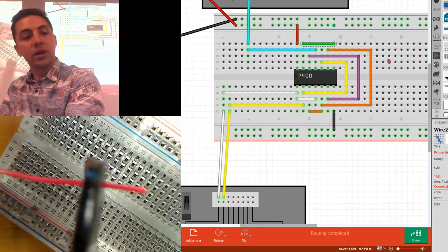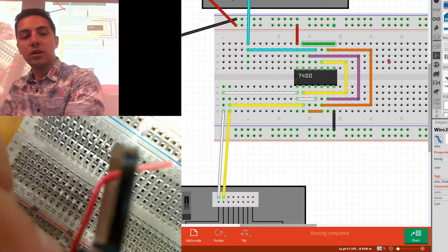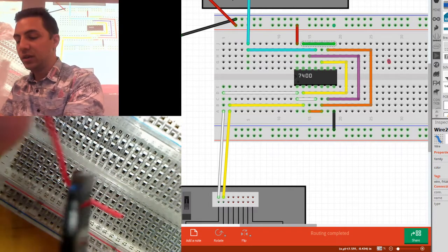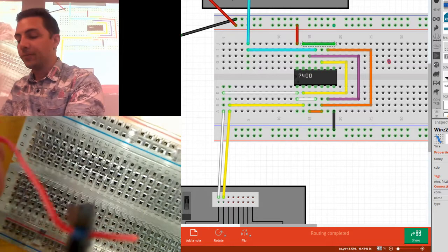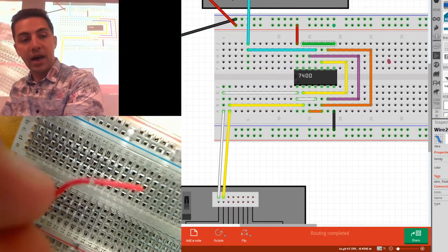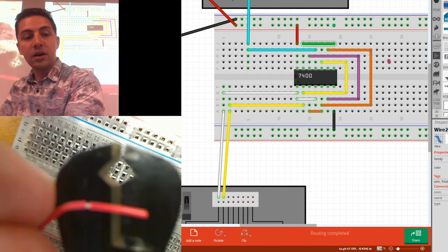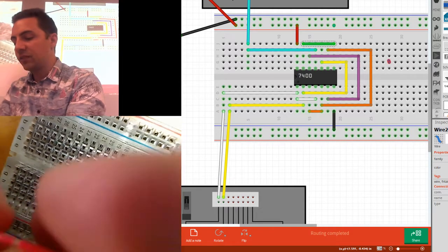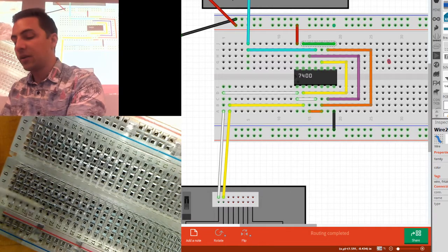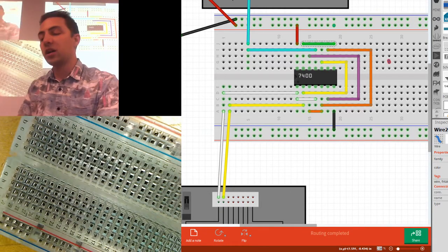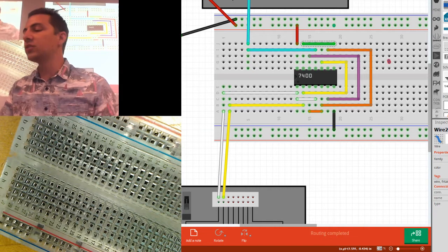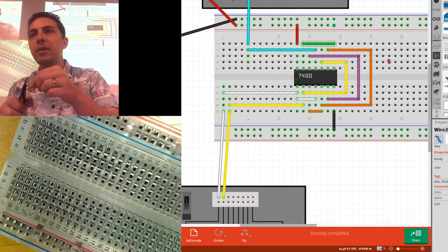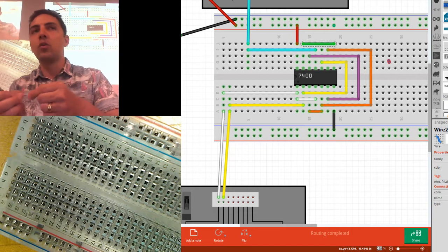So what I do is I put a small joint into it. So now it's bent there. It's also bent on my fingers. And I turn it like a crank. At that point, if I just remove that, hopefully you can see the insulation has already been separated. Can you see this little silver there? If I wanted to, I could just take my fingers and remove that. Okay? But it just makes a nice clean cut on the insulation. If your pliers aren't properly adjusted, you'll bite into the wire a little bit, and it will cause a score in the wire.